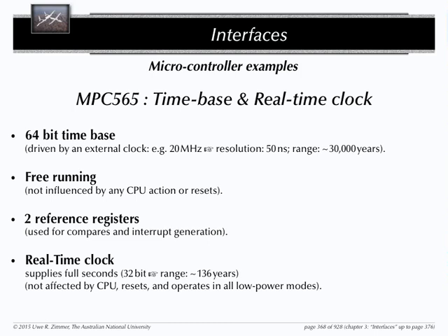How free is that? It's so free that you can do whatever you want with your device. You can program as hard as you want to try to influence that one. It will not budge. It will not move. It will not even respond to a reset. It's free running, and that gives you the hardware guarantee that you can depend on this counter as a reference for your real-time environment. This is your generated real-time on your chip, because you have a guarantee: no interrupt, no software instruction in your CPU will ever touch that thing.